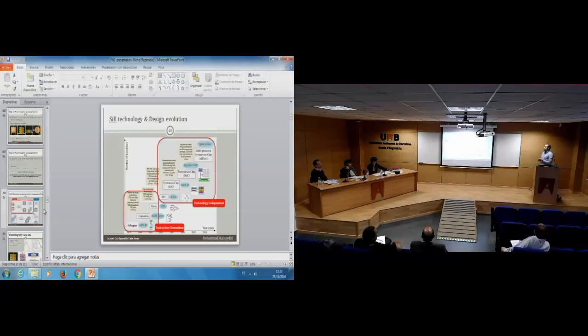Gate arrays are not built of complex gates, but they are built of transistor arrays, being later on customized for final circuit functionality. So we are taking the same concept from silicon gate array, which is built of transistor arrays, and we are mapping that to organic electronics. But yeah, it could also be named inkjet configurable transistor array, and when we have cell-based gate array, we call that inkjet configurable gate array.